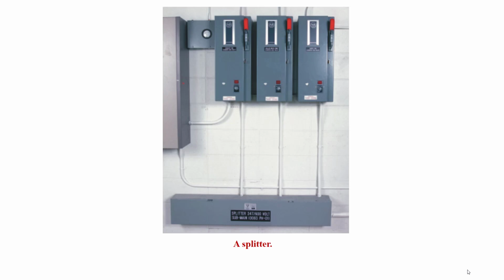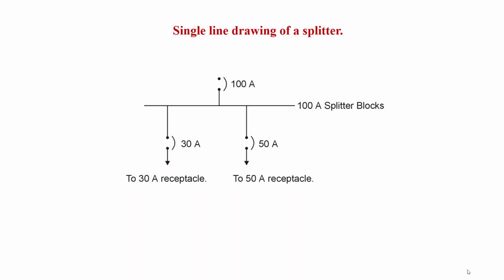One of them is for these tap conductors, or smaller wires, that are less than 3 meters long. Here's a single line drawing of a splitter, and particularly we are focusing today on right here where we terminate onto our splitter and our first overcurrent, and the length of this wire when it's less than 3 meters long. So we don't have to put one right here. We can put one within 3 meters if we apply these rules of 14-100(b).